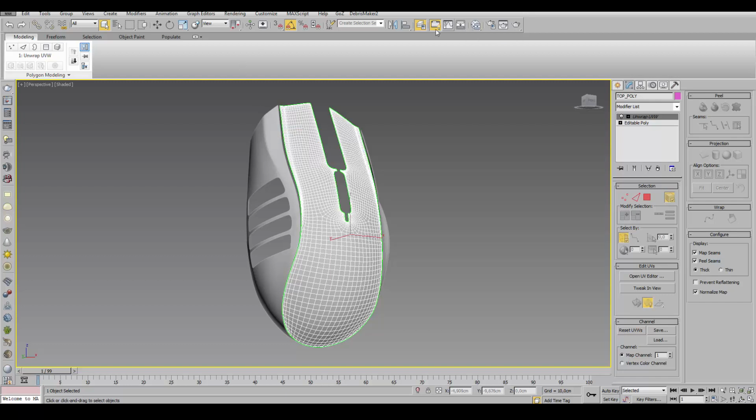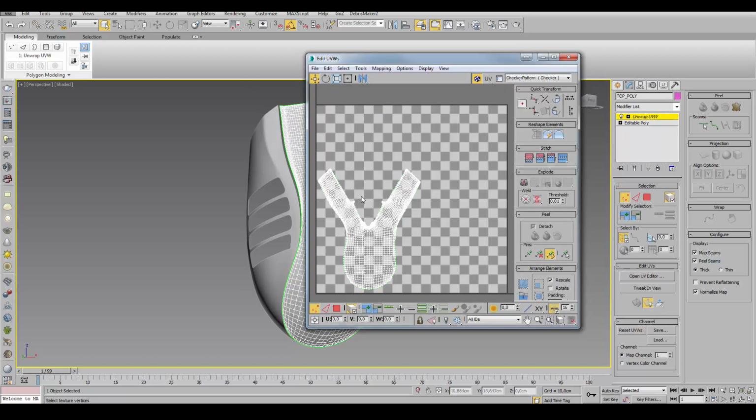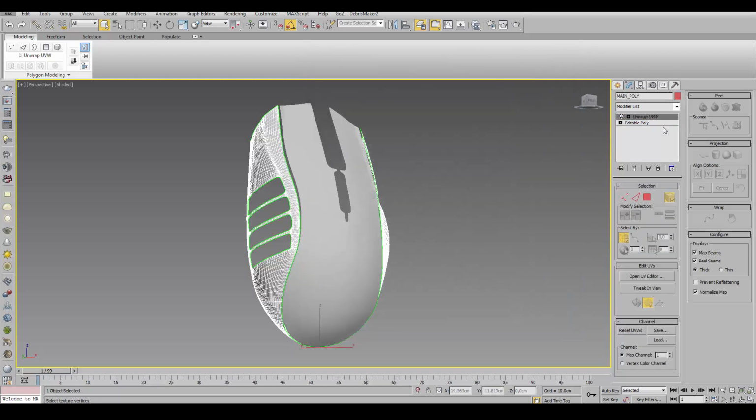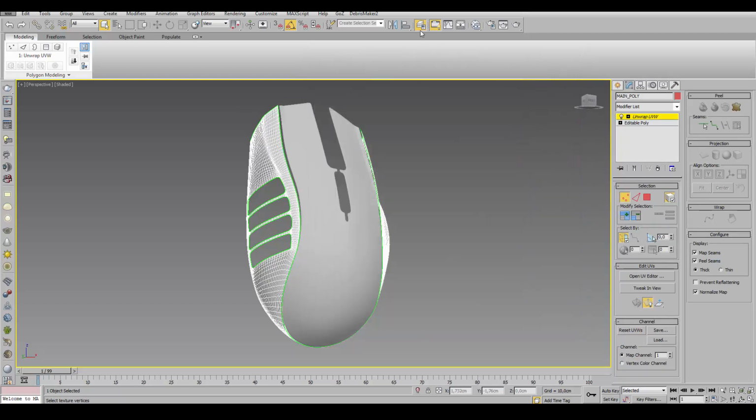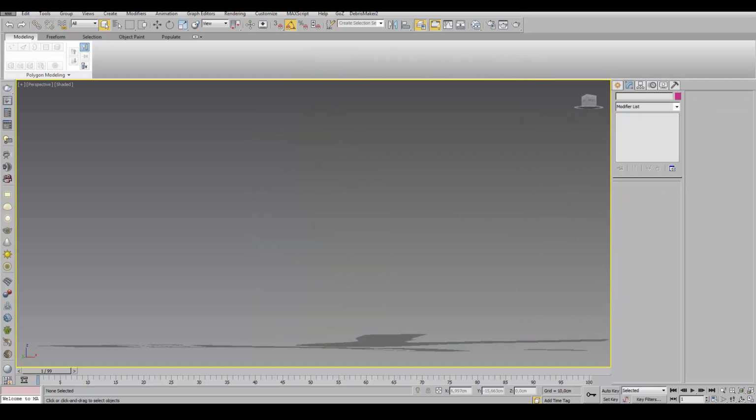So basically I said, okay, I know that there's a way for sure that we can convert this model to a flat version using the UV. So first thing first, I made the UVs, and I made the least deformed UV possible. So I used the standard unwrap system, if I remember well, directly inside 3ds Max. I don't remember if Max or Maya, but it doesn't change at all. So I made the least deformed UV that you can create. It was a flat version of this model, a flat version of the side model, and things like that. So I created just a simple UV, a flat version of the UV. And I ended up with something like this.